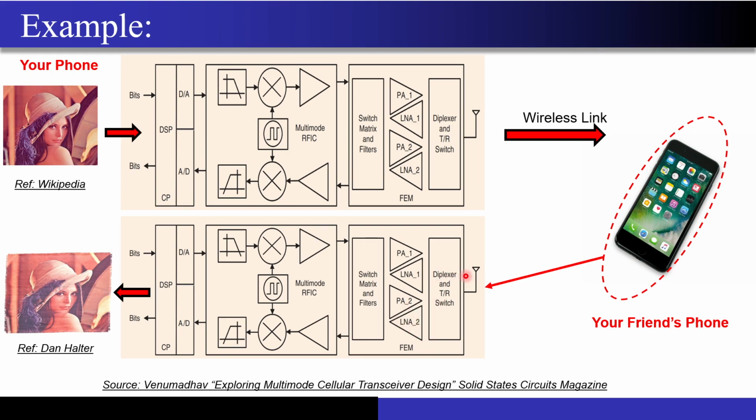And what is this diplexer and all? See, this is complicated circuitry. You have to transmit not only on 4G, but if the 4G band is not available, your phone should be able to transmit on the backward generations, that is 3G or 2G as well. So these diplexers combine the signals from multiple bands and allow those signals to share the same antenna. Of course, it assumes that the antenna has a bandwidth which can carry all those bands.